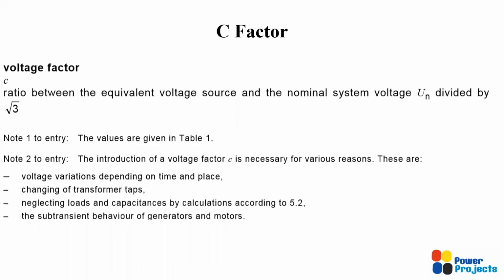Even if it's a time varying impedance of the generators, that you can put X_T double dash or X_T dash. But what's the voltage which we need to take? So if we take it as 1 per unit or 100% voltage, then do you think that just prior to the fault, the voltage at that particular fault point is 100% or not?